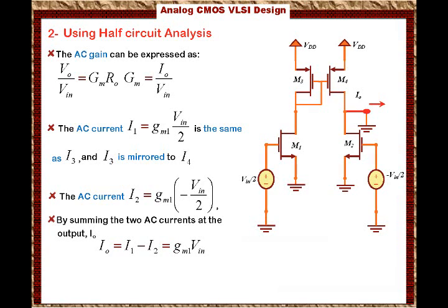But also we know the transconductance Gm of the amplifier is the AC output current over the AC input voltage, and in this case when we divide by Vn we have GM1. So for this particular amplifier, the transconductance of the amplifier is the same as the transconductance of transistor 1.